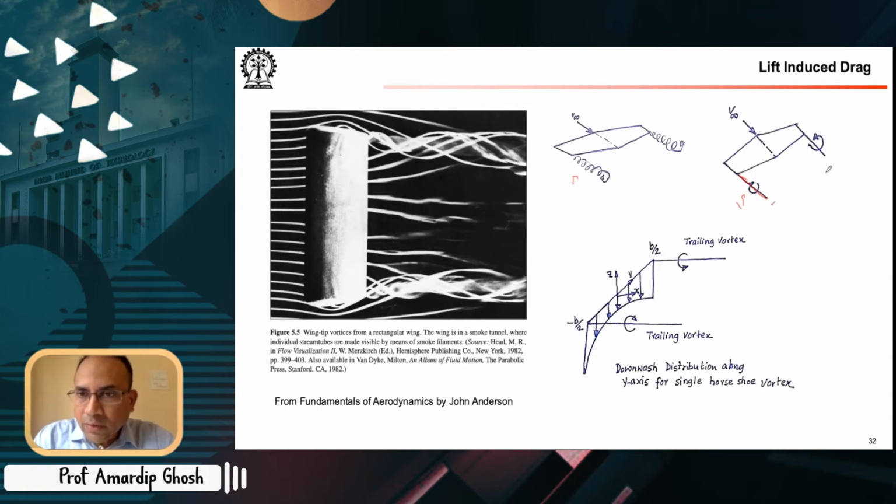So once again, these are vortex filaments. The circulation is the same as what is developed in this, and you cannot just draw a filament arbitrarily. So you have to understand the direction of the vortex lines, etc., to create the filament. Now we have this trailing vortex represented by a vortex filament.